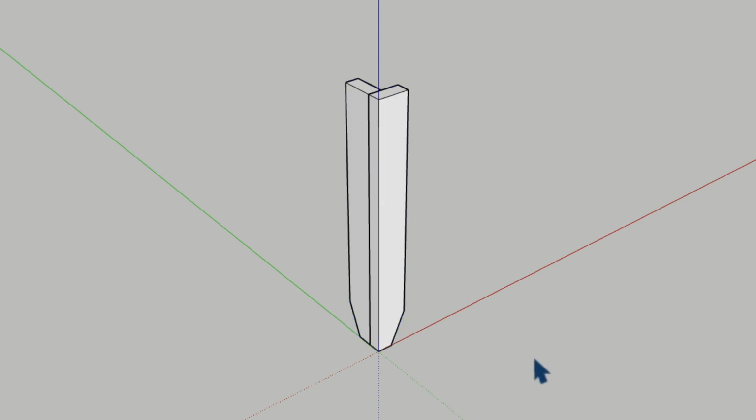There's another type of selection, though, that we just used a moment ago called a crossing box. If we click over here on the right and drag up to the left and just make a box that crosses these two items, you'll see that they're selected. This is called a crossing box. We used it a moment ago to delete one of the guidelines. But we can use either method to select. There's actually three methods. One is to draw a box around both items, one is a crossing box, and the other is using the Shift key.